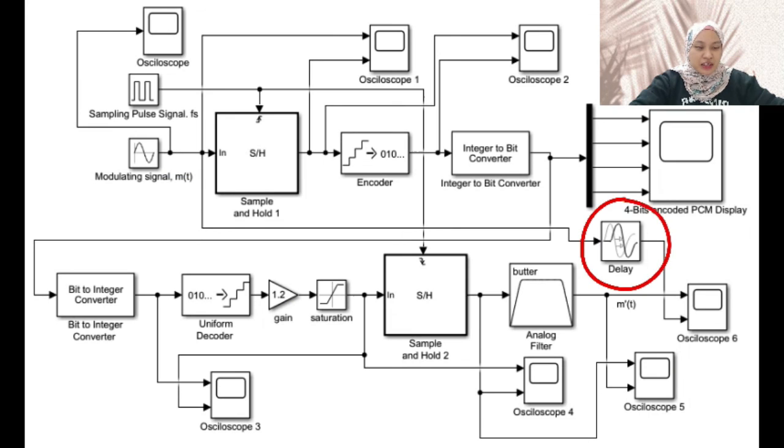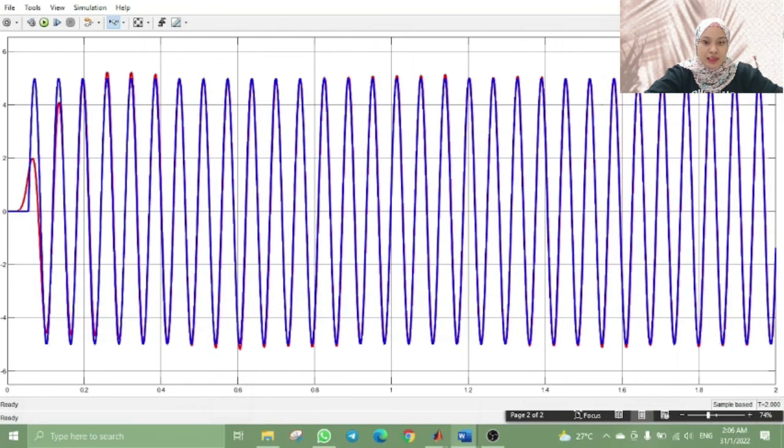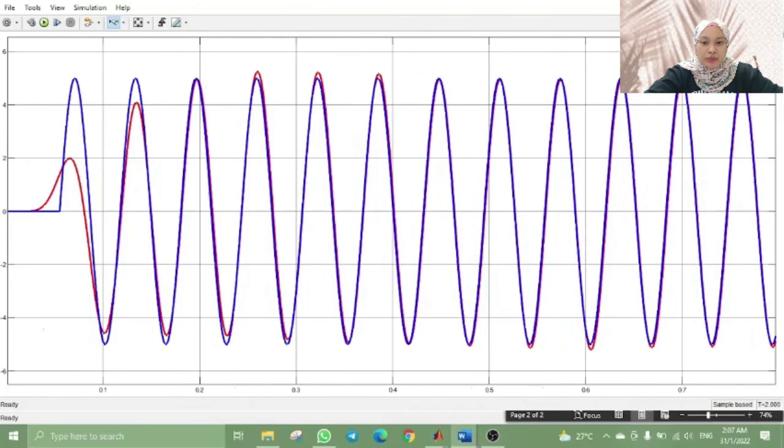The block produces the initial output parameter at the start of simulation until the simulation time exceeds the time delay parameter. The block then starts creating the delayed input. The delay block saves input points and simulation times in a buffer during simulation. The initial buffer size parameter specifies this value. This is the outcome of similarities between two waveforms. The waveform of the resultant recovered modulating signal, which is the red one, is almost similar to the analog modulating signal, which is the blue one.